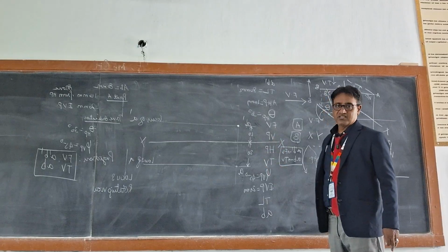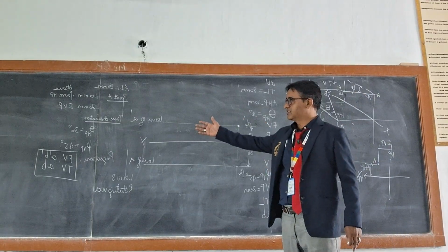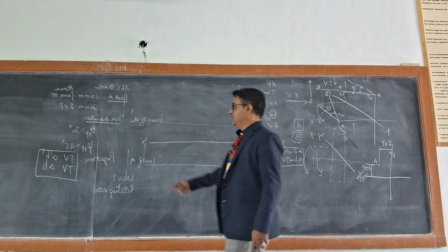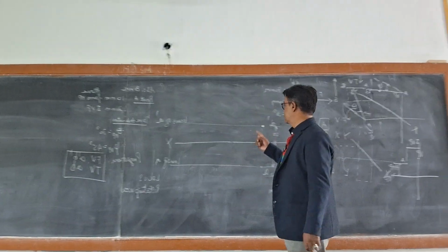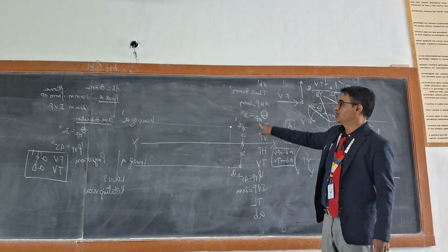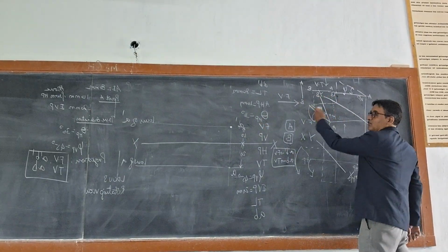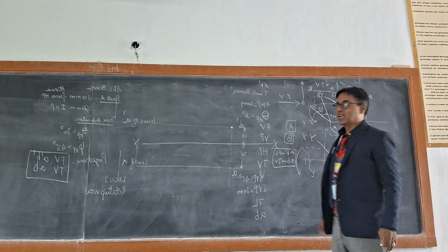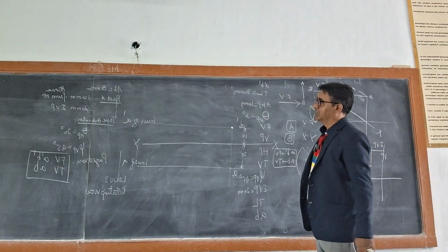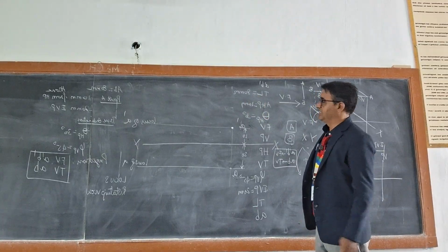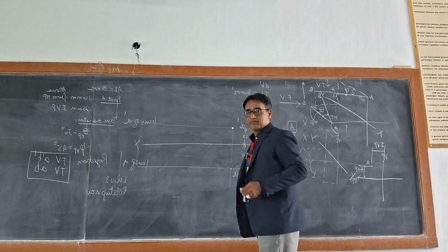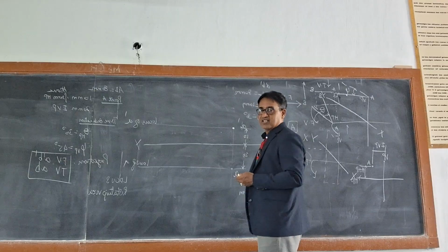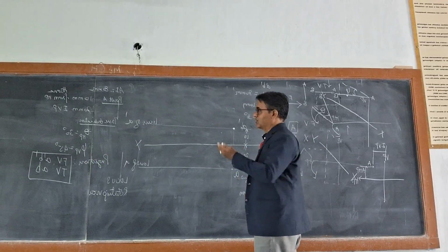Then next, you look at the other data which is given. True length is given and true inclination is given. First understand, any inclination to HP will be above XY, because in the format, inclination to HP is viewed from the front only. Therefore the front view is above XY, so there I can draw the inclination, for which the true length is also given. The true length is 80 mm and the inclination is 30 degrees. So take your compass and protractor, measure a length of 80 mm, and incline that line by 30 degrees.